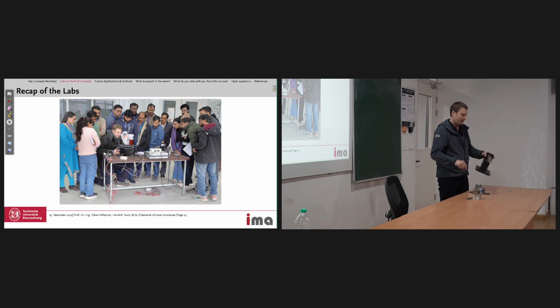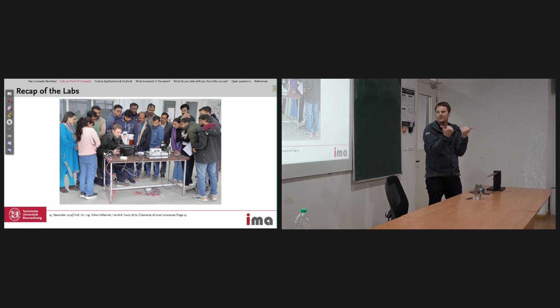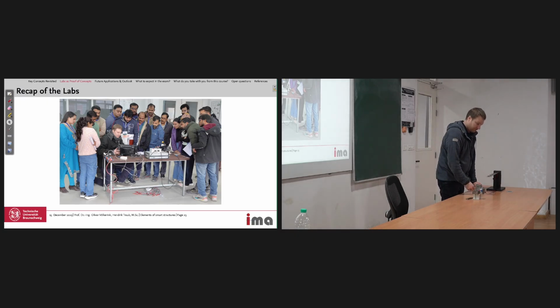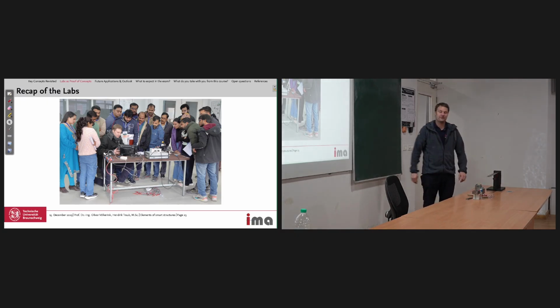This is a D3 actuator, where you have two electrodes like this, piezo material in between, polarized like this, but actuation like this. Okay, so actuation not in the same direction as the electric field or as the polarization, and this is why also the effect becomes less, because it basically works with the contraction in the opposite direction. Okay, this was our third experiment, and today was the first day where we used some dynamic testing.